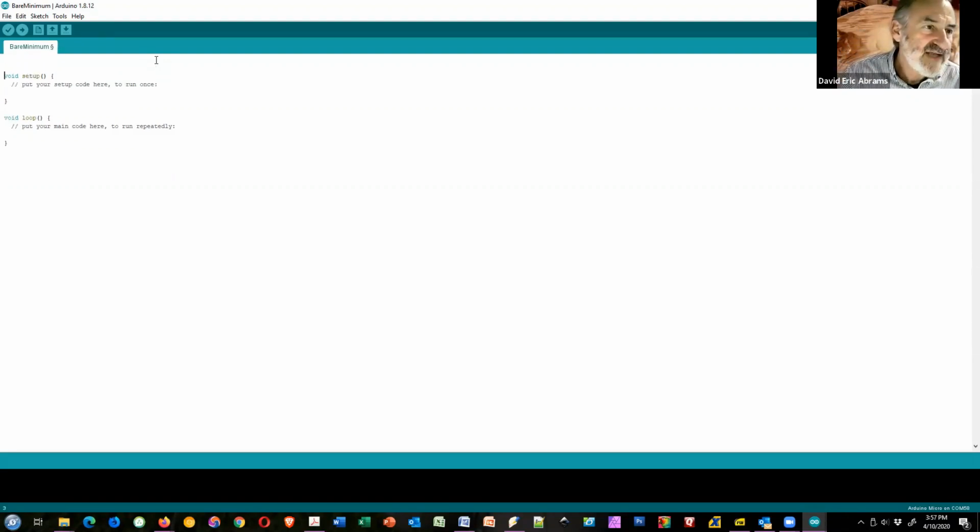Now, what does code consist of? Let's start by saying we're going to define a variable. In this case, I need that variable to be an integer, so I say int. By the way, when you see it in light blue like that, that means it's a keyword, a special word that's part of the Arduino language. If I wrote integer, it's black. That means if I think I'm using a keyword and it's black, I made a mistake. So the first hint, int, says I'm going to define a variable, and I'm going to call this LED pin.